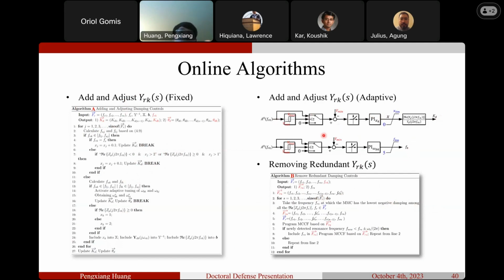In the DCE, I proposed to use an adaptive method to regulate the gain and the bandwidth. The idea is using a PI controller, but what is the input? The input is the error of the spectral peak value. The spectral peak has already been identified as an oscillation. That's the requirement. Then you compare this with a threshold value, the same threshold value you used before to identify that oscillation. You put the error into the PI controller, and it generates a gain.